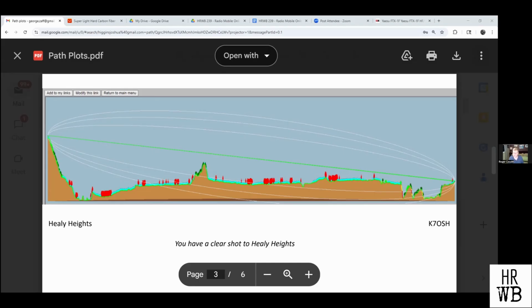You have a mountaintop repeater in the middle of the Rocky Mountains with a solar panel and everything, and you have a preamplifier in the line. Then you can say I have 0.1 microvolt sensitivity. That is possible. But when you're in the city, forget it. You don't have that on the mobile side. You have that on the repeater side. Then you have an asymmetrical communication, because the system gain is not the same in both directions. So normally I use the worst case.